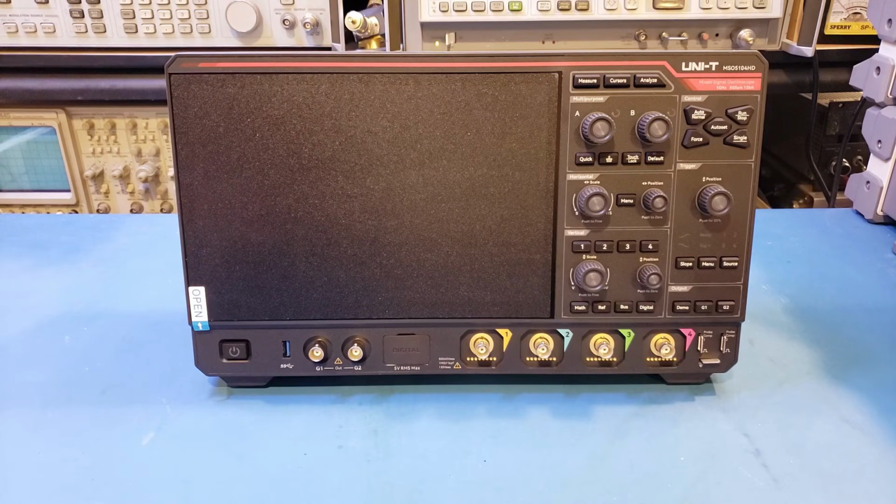I'm not going to give you an exhaustive list. If you wanted to dive deeper, you can refer to the excellent datasheets on UNI-T's website. But here are some of the highlights. For instance, just to name a few, the MSO5000HD has better DC gain accuracy, higher external triggering voltage tolerance, it added additional measurement parameters and timing analysis, and the function generator has a higher sampling rate, 312.5 megasamples per second versus the 250 megasamples per second in the MSO3000X and 3000HD series.